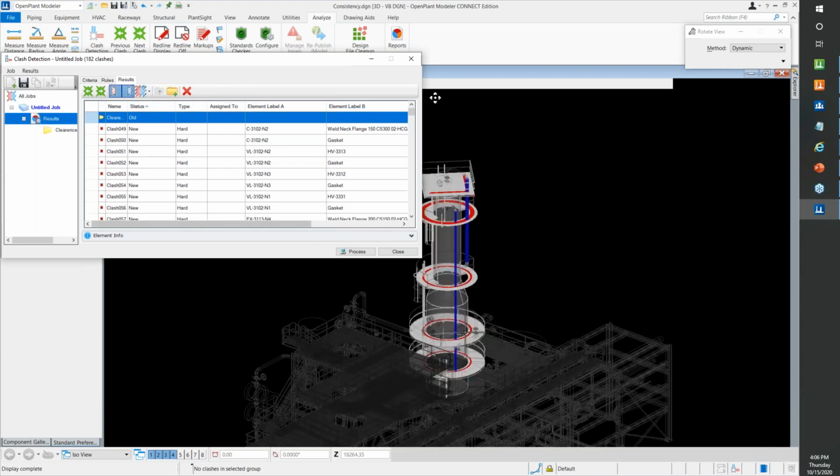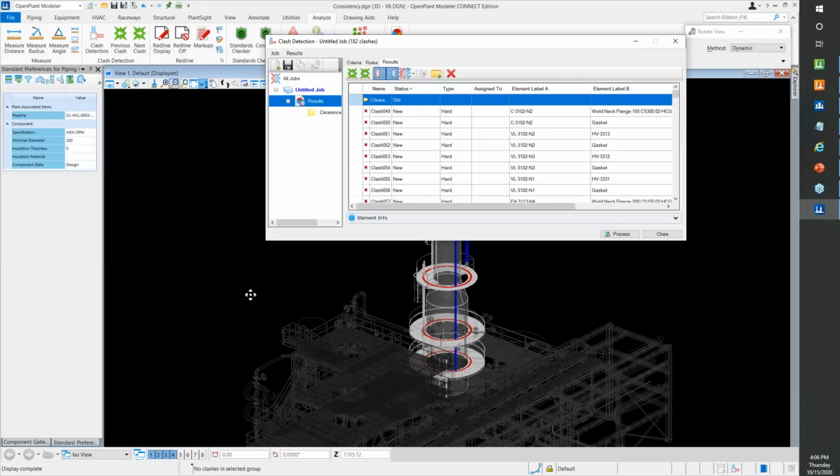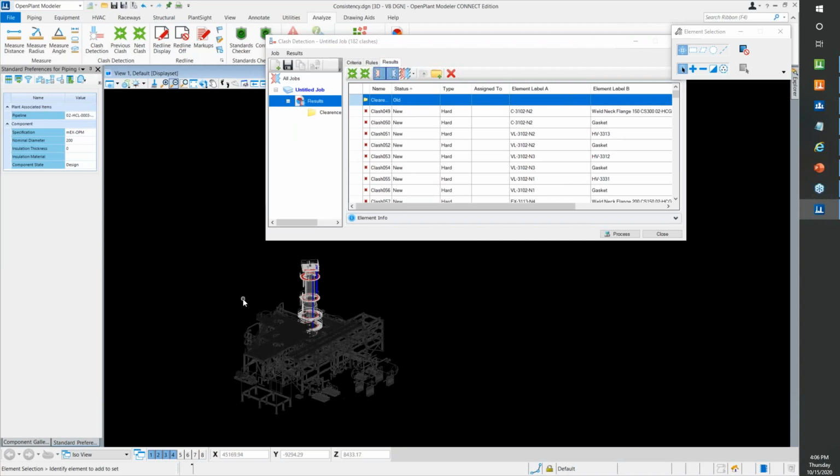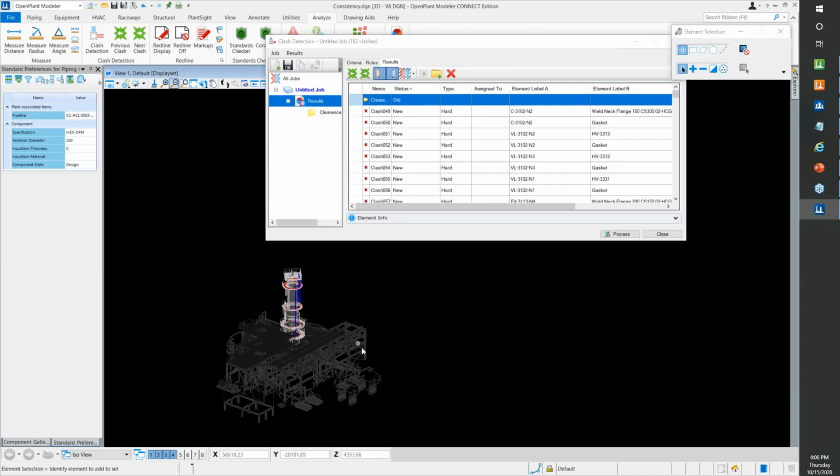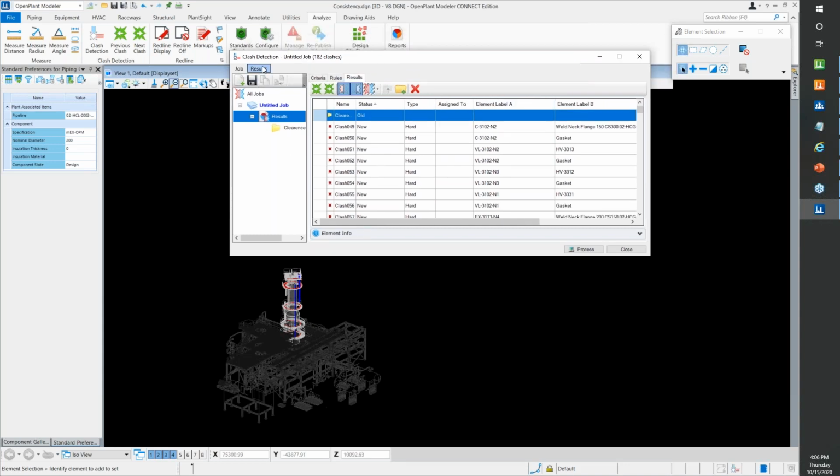Further, you can do the clash detection in your project to make sure that your model is clash free at the time of design, as well as avoiding the critical scenario at the time of construction. And these results can be exported to different formats. One is Excel or CSV, as well as the other format is GPS coordinate system.